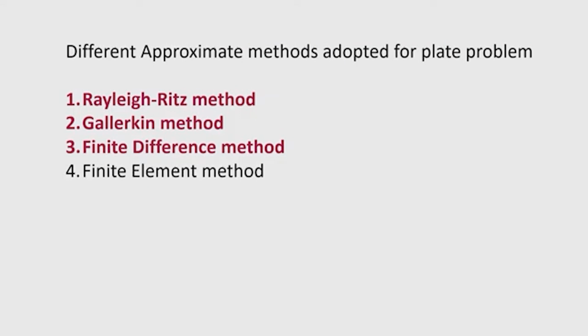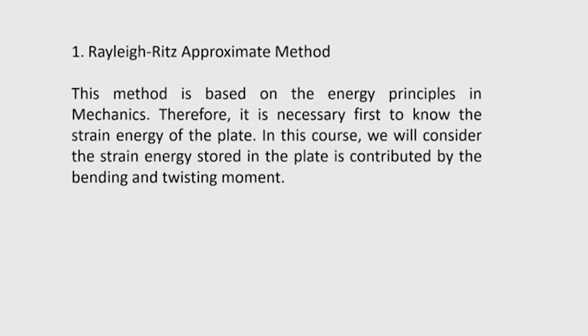Now, let us see the first one, Rayleigh's method, in detail. This method is based on the energy principle in mechanics. Therefore, it is necessary first to know the strain energy of the plate. In this course, we will consider the strain energy stored in the plate as mainly contributed by the bending and twisting moment.